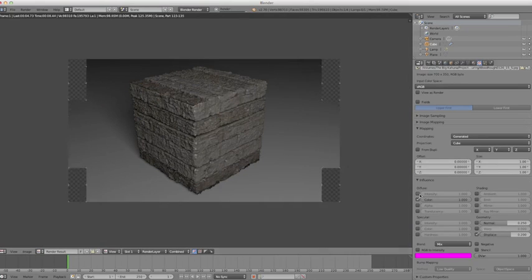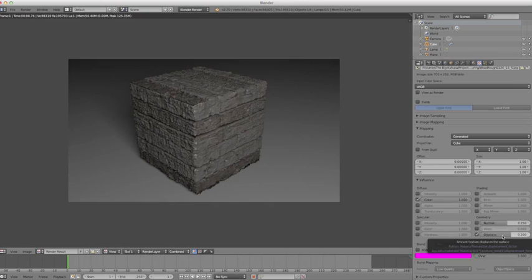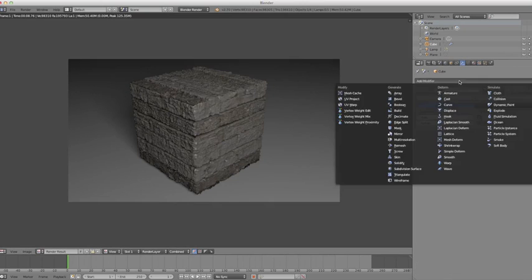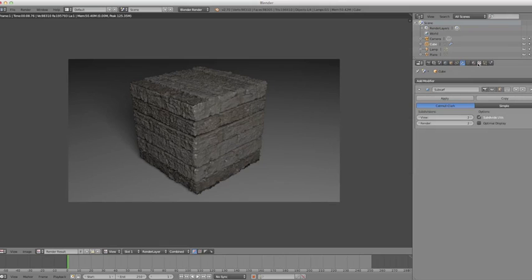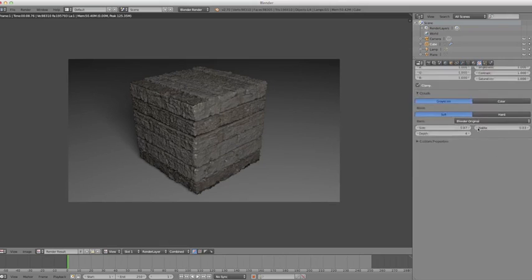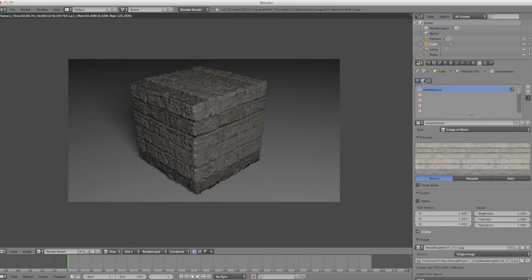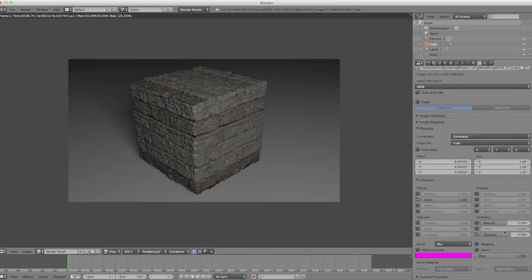And the difference is normal is going to distort just the flat surface to give it the illusion of depth within these cracks here. If you actually applied the displace map with the displacement modifier that you see under this menu, then right here, then what you're going to get is the same effect that you see over here with the texture that we've generated, but it's actually going to write that information into the geometry and distort it permanently.